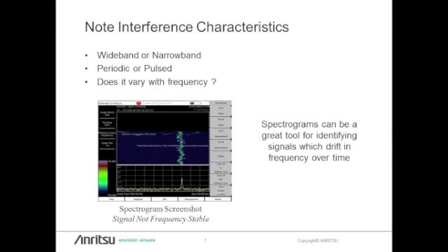And for this kind of measurement, I'll get a little bit ahead of myself here. You really need to do a channel power measurement. So if you're doing a zero span or very, very narrow band and the frequency is drifting, you're not going to see it, you're not going to catch it as you do your interference hunt. So it's absolutely essential that you have a bandwidth that is at least as large as that frequency drift. And we've seen from our experience, and we need to incorporate in the systems that we develop for interference hunting, a good channel bandwidth measurement.